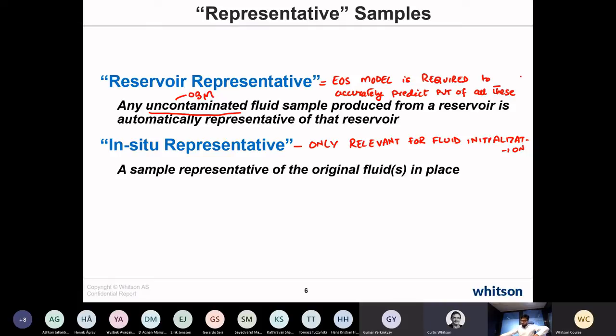So we have an equation of state that has a component slate of the in situ reservoir components and another component slate of only the oil-based mud. And then for each sample with PVT measurements, you assign the distribution of the oil-based mud components and do the modeling with that. When you're done modeling, getting all of the PVT measurements modeled accurately with this, call it hybrid equation of state, once that's done successfully, we simply take all of those samples we have that are contaminated, we throw away all of those